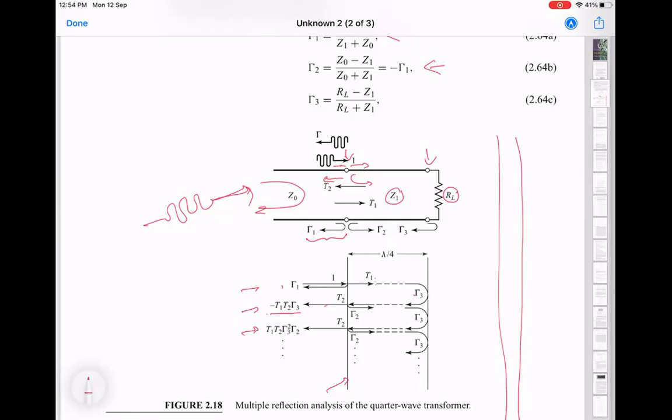Hence, you can never get a situation where, when a wave starts, you're going to get no reflection. Just like when we talked about an LC resonator, where in steady state it reflects the full power back, but it needs to first build up some power to reach that steady state. So that is a transient aspect. Similarly, this will also have a transient, but it quickly dies down. So we can stop there.